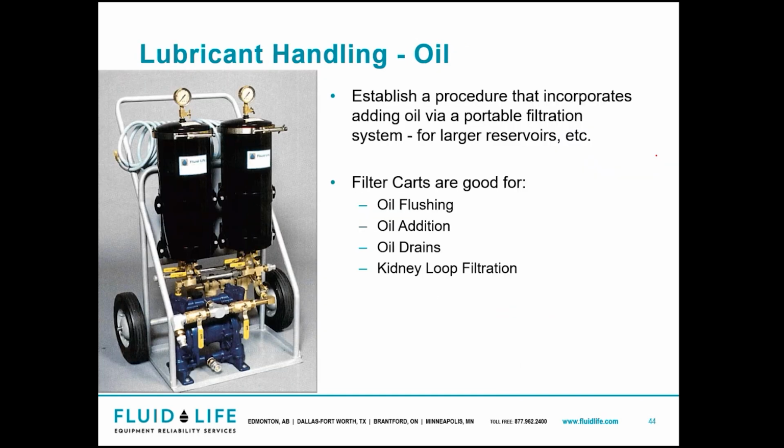And lubricant handling, when it comes to establishing your program, portable filtration, especially on larger reservoirs, is just going to make your life way easier. Filter carts are huge. I had a site that I worked at for a number of years. They were emptying drums with a hand cranked pump all year long until I bought them these. Their arms had to be just dead from hand cranking. I'm like, buy a pneumatic pump, buy a pneumatic filter cart. Then the oil gets filtered, so you have clean filtered oil going from your totes and barrels into your equipment storage.